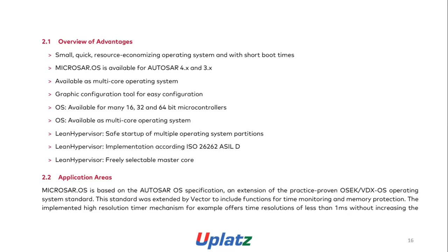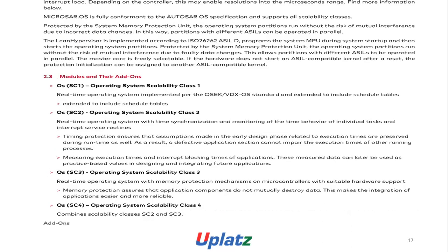Application areas. MICROSAR OS is based on the AUTOSAR OS specification and an extension of the practice-proven OSEK/VDX OS operating system standard. This standard was extended by Vector to include functions for time monitoring and memory protection. The implemented high resolution timer mechanism, for example, offers a time resolution of less than 1 millisecond without increasing the interrupt load, depending on the controller.